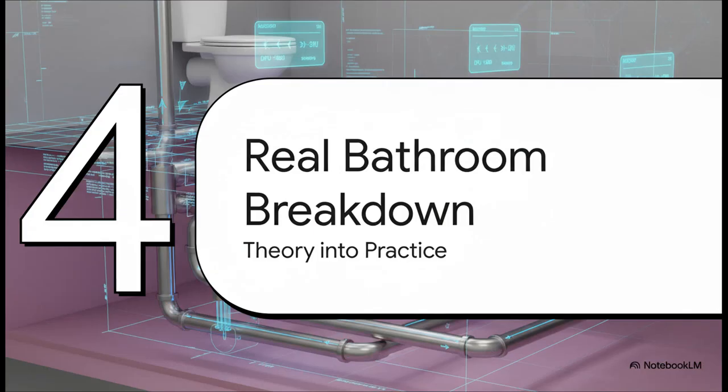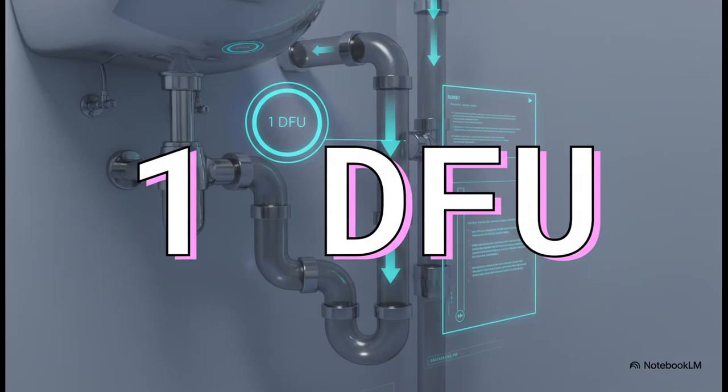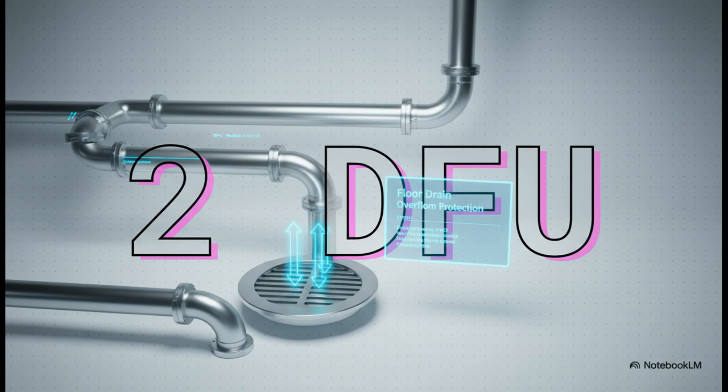Okay, enough theory. Let's see how all these ideas and rules come together in a super common, real-world scenario. Let's design the drainage for a standard bathroom. Right, first things first, we start with the fixture that has the biggest load. That's the toilet. According to the code, a standard toilet gets a value of 3 drainage fixture units. Next up, we've got the wash basin. You know, the sink. It's a much lighter load on the system, so it's only assigned a value of 1 DFU. And finally, we have the floor drain, super important for cleaning and preventing overflows. This one gets a value of 2 DFUs.